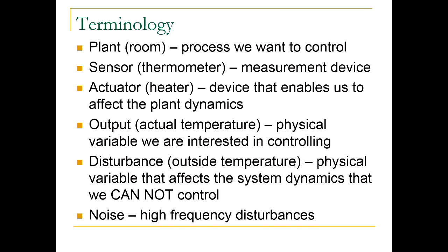The disturbance, in this case, is a variable you can't control, but it still affects your system. So for instance, in a car example, cruise control example, the slope of the road is a disturbance. If you drive on a flat road, it's different from when you're driving up a mountain. So you need to press the accelerator a bit harder to maintain the speed, right?